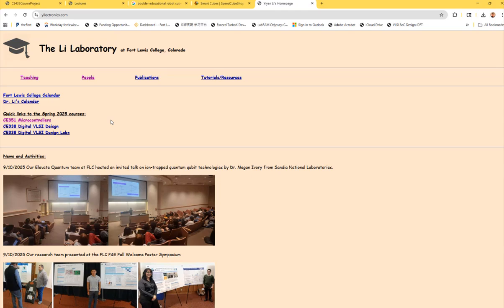Nope. Because it's a continuity check, right? You want to hear the beep. You change the multimeter to the contact option at the bottom, which is a little bit different channel on different multimeters, and you can do a continuity check. You hear the beep, which means they are shorted together. So the ground pin of the chip has to be connected to the universal ground of the board. You have to hear the beep, okay? So that's how you verify power and ground.